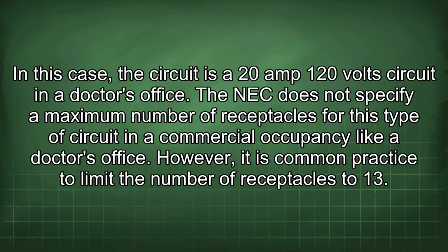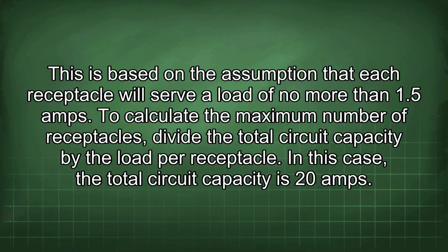In this case, the circuit is a 20 amp 120 volt circuit in a doctor's office. The NEC does not specify a maximum number of receptacles for this type of circuit in a commercial occupancy like a doctor's office. However, it is common practice to limit the number of receptacles to 13. This is based on the assumption that each receptacle will serve a load of no more than 1.5 amps.